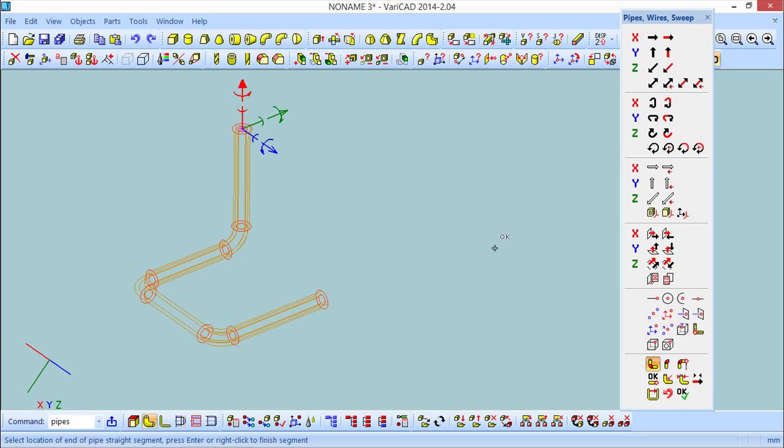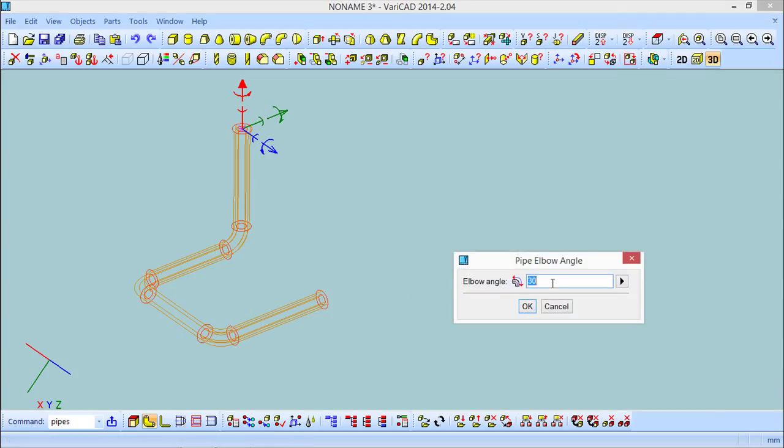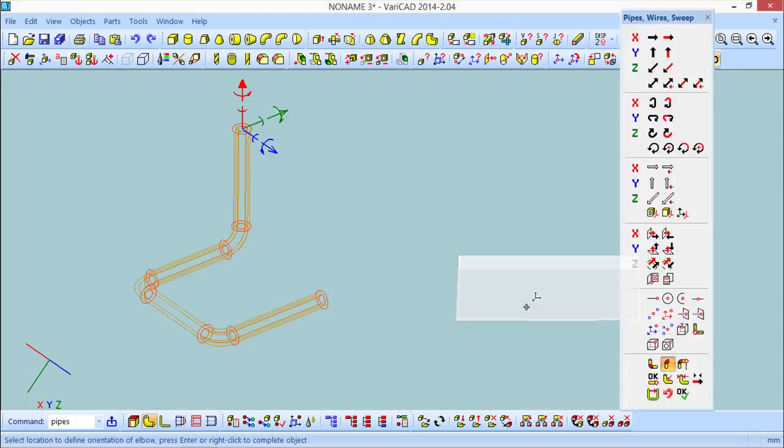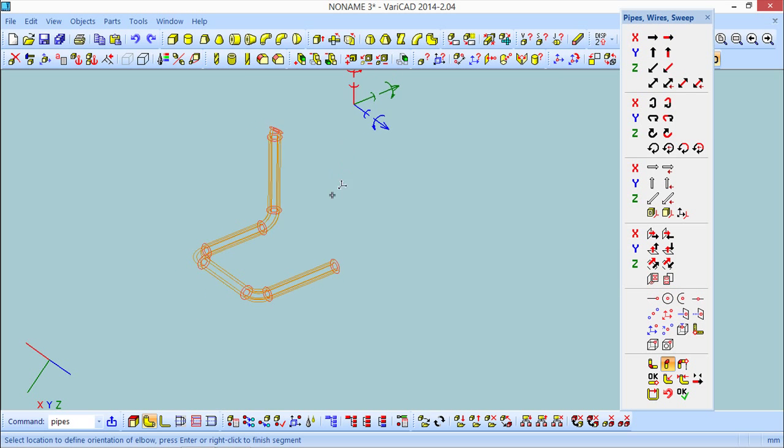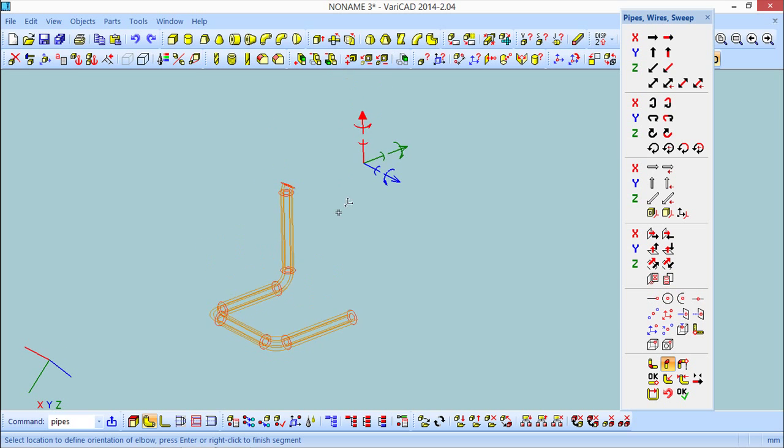First, I'm building this pipe, and this is the basic mold that I'm doing, straight elements and elbows. I could do this elbow by start tangent endpoint, where, for example, I just need to give an angle, for example this 30 degrees, do the OK. And now if I go, for example, in this direction, you see that it has done an elbow like this, okay?